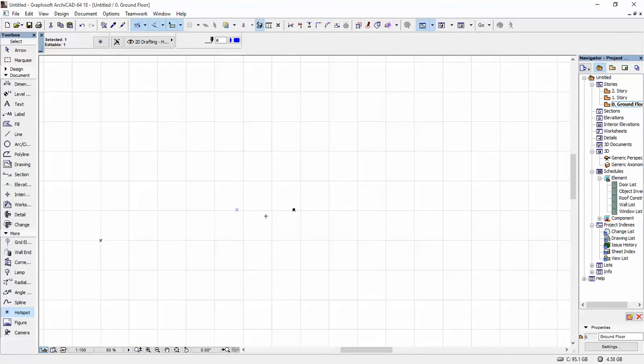The next thing I'm going to do, I'm going to keep this one selected and select the one that I drew first. And I'm going to hit the drag a copy again, but this time I'm just going to use the shortcut Control, Shift and D. I'm going to click over here on one of them and move upward, let's say 2 meters. So this is going to be the unit of your fill. What's going to be inside here is going to be the pattern.